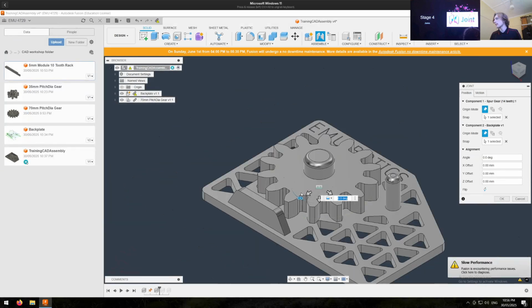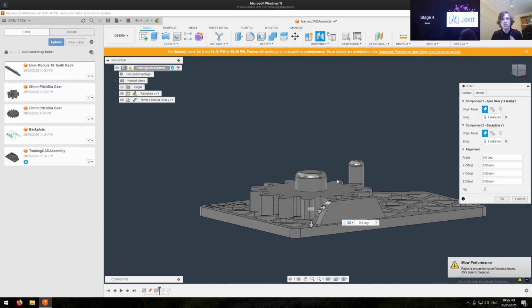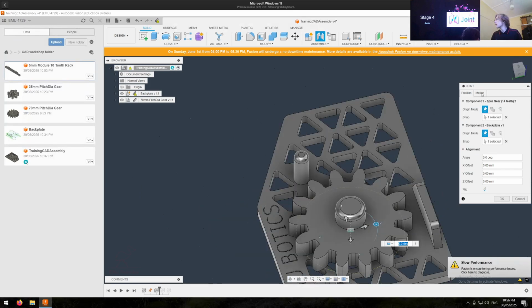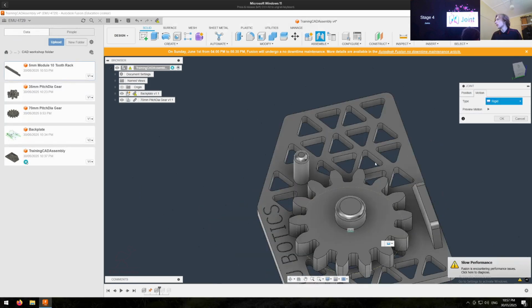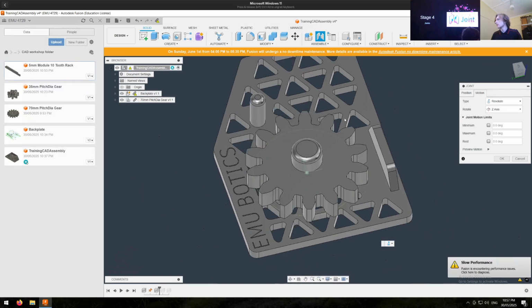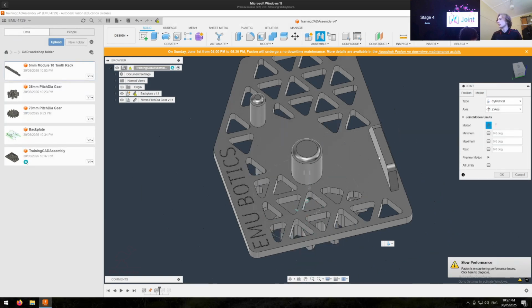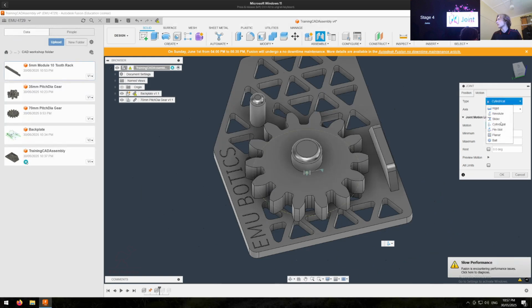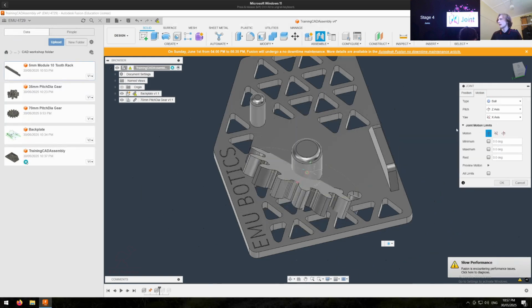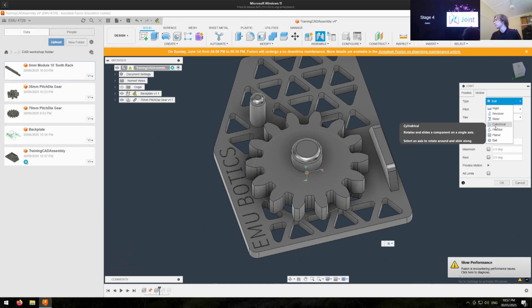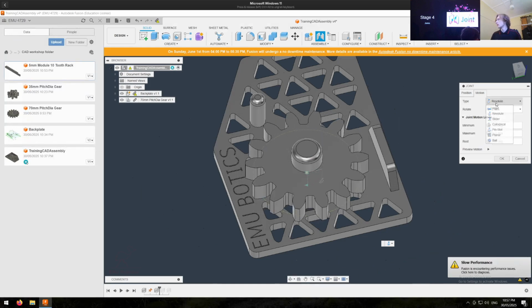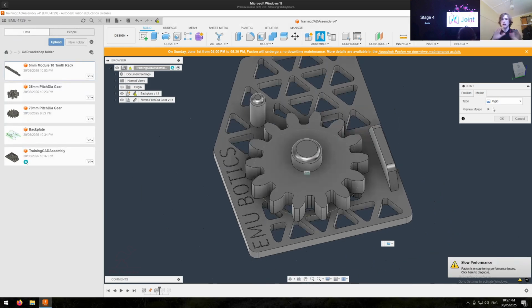And look at that. Instead of having to use the move tool and kind of fudge things around, it just works. So now we can use, say, Revolute, and you see how this starts spinning. Or you can use different types here. Explore, have a try out. You see cylindrical, and it's moving in all weird ways. Or you can even do ball, and that's broken. That's not working properly. And with rigid, it shows you that the two parts will shake together.